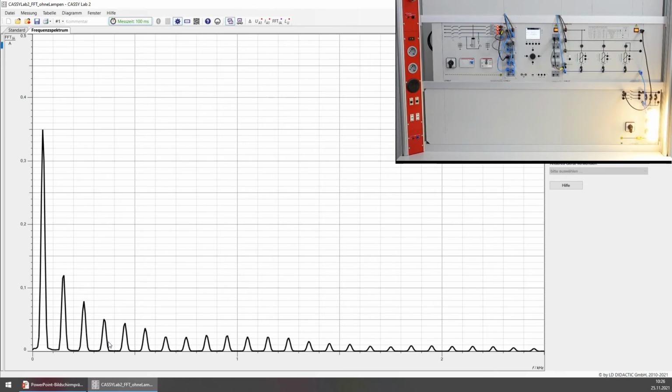Then you see we have many harmonics at every order up to the 5th order, especially at the lower orders as expected at 3, 5, and 7, but also every other order is affected. With the Power Analyser Plus, we would be able to measure the harmonics even higher, up to the 100th order, but this is not really relevant in power engineering.